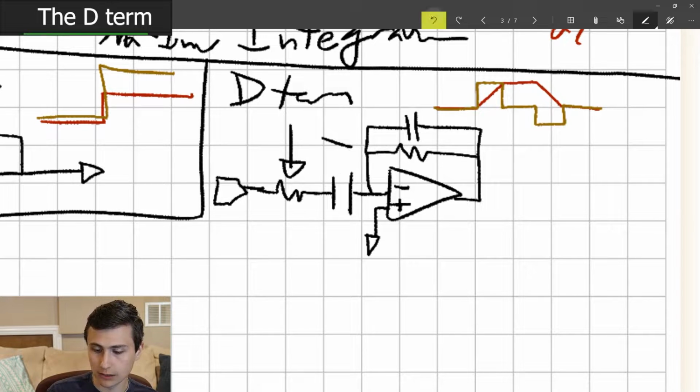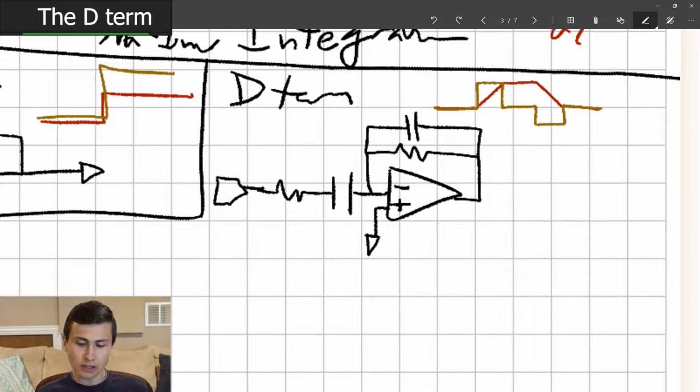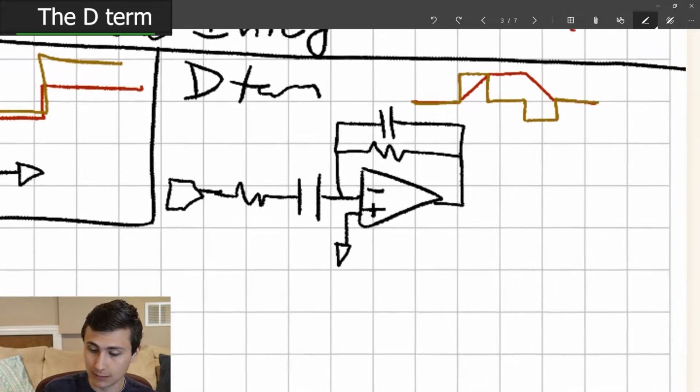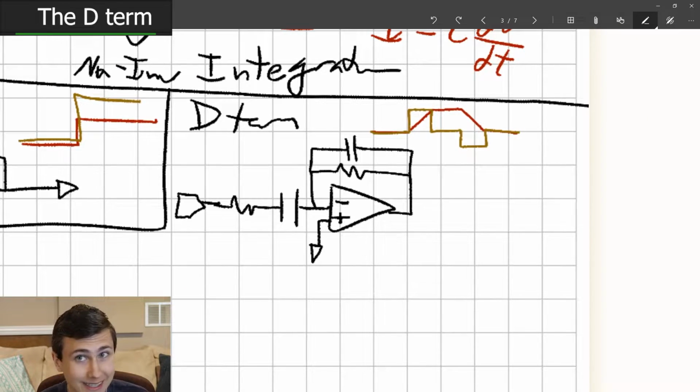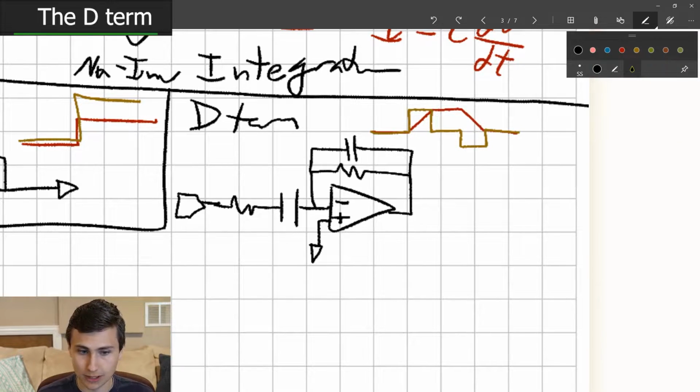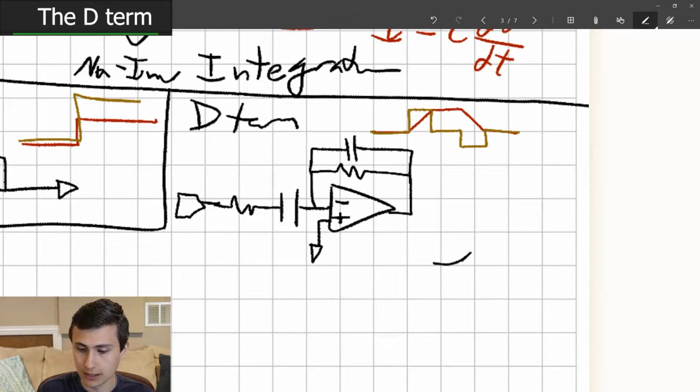But then there's kind of this weird thing that happens where depending on this resistor value and that resistor value and these capacitors, changing any of these components, the capacitor, the resistor, it changes both the wave shape because we're filtering the input signal and also the amplitude. So if we want to have a way to only modify the amplitude, what I like to do, and maybe this is just me being lazy, because we already need to invert the signal, is add an inverting amplifier stage at the end of this.